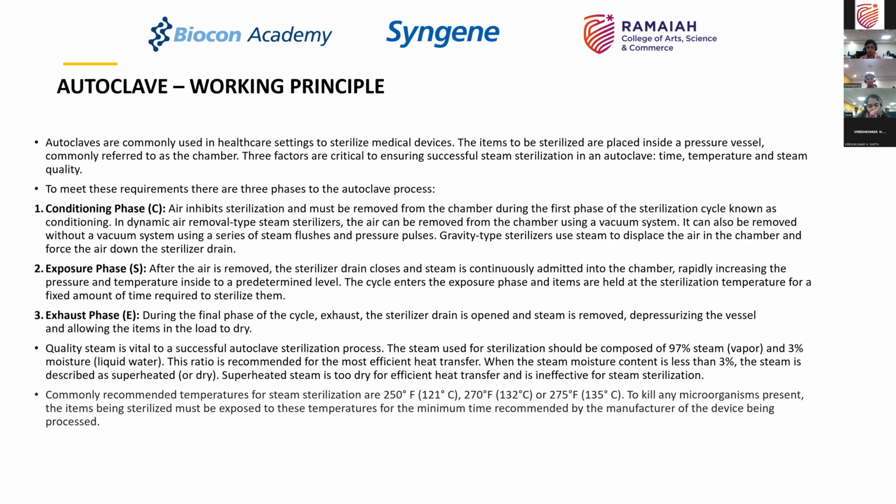as I said, because remember that in any manufacturing environment, you are not going to have the temperature stay fixed at that 120. Why is that? Because once you enter the hold time, there will be a dynamic situation inside the autoclave where some amount of condensation occurs. So the temperature tends to drop, or the pressure tends to drop. In such a situation, you need to inject steam in pulses into the autoclave during the hold time itself, so that it maintains that 121 degrees centigrade.